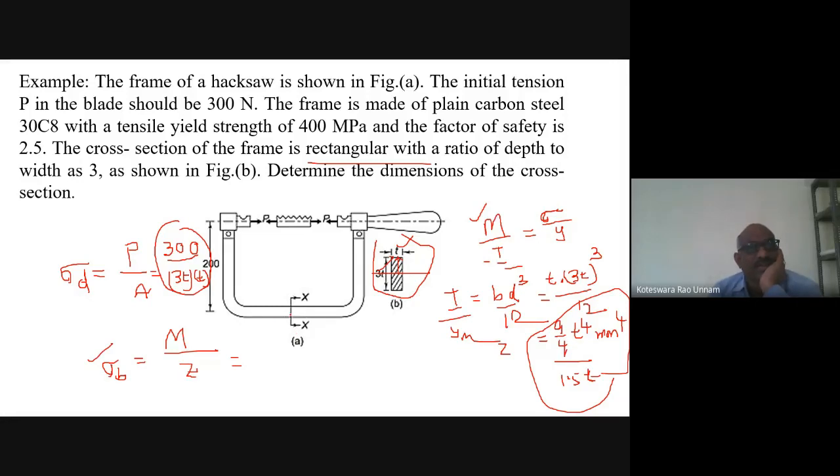So for that, direct stress is acting on the cross section something like this, towards the cross section. Because this force is acting like this, it will also act like this. So your direct stress is a negative value. Then bending stress. We already know the bending is about the z-axis.